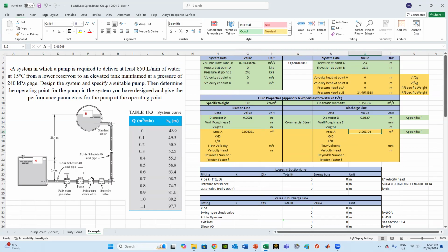I assume it here is clean, so I need to go to a special table available within the friction losses. So I'll tell you which chapter. For that one, we go to Reynolds number, laminar turbulent flow and energy loss due to friction, chapter 8.